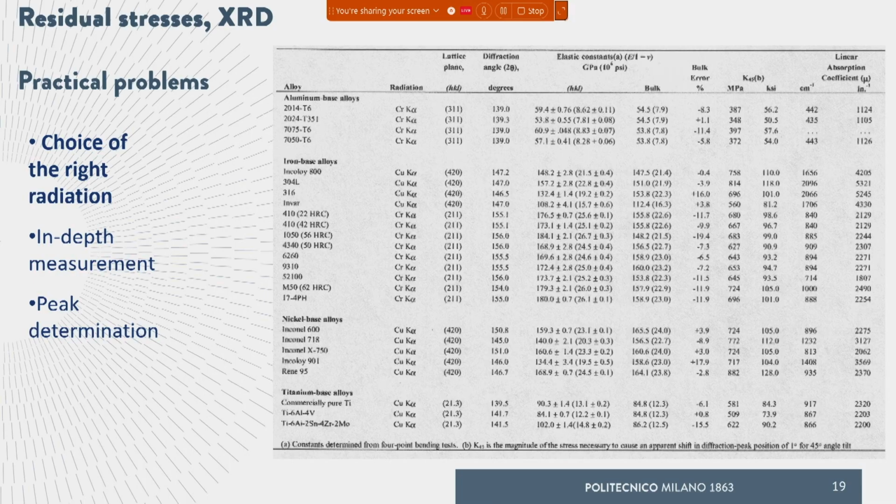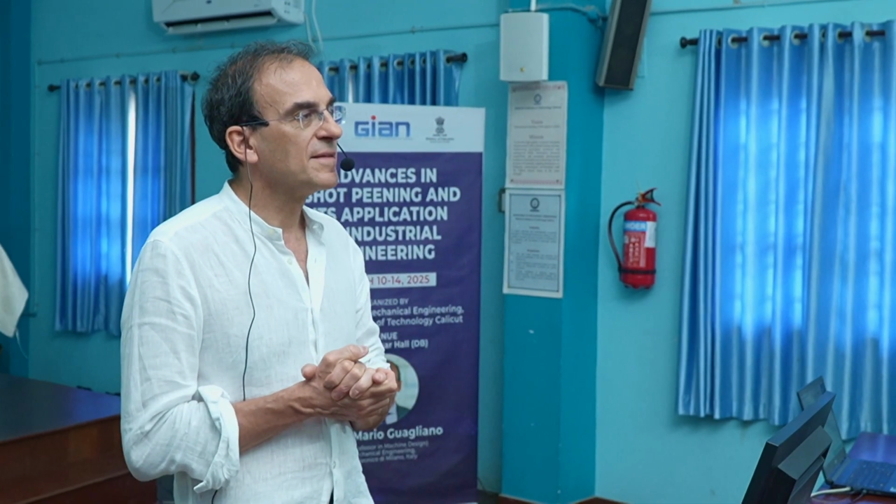Because, say for example, the last one, Ti6Al4V at the bottom, if we actually try to figure out the XRD pattern of Ti6Al4V, we could actually get it between 10 to 90 degrees diffraction angle. But here, I think they have gone up to 140 something. So what might be the reason we are going for this diffraction angle? Why we are actually making the XRD go in? Why we use this angle, you mean? Yes, sir. Because normally, if you are trying to get the peaks of titanium or vanadium or the other alloys, we would get them between 10 and 90 degrees.